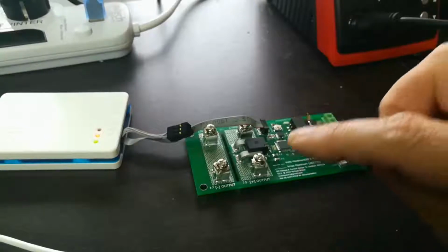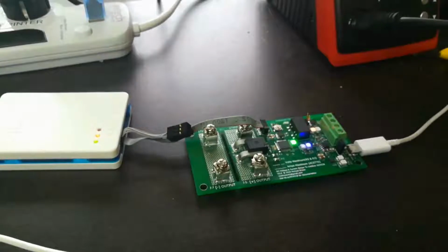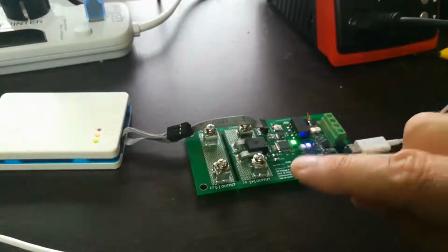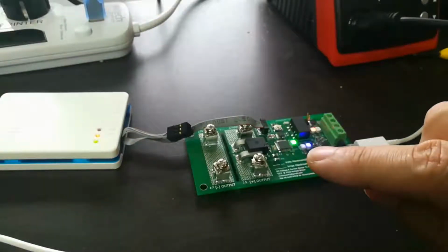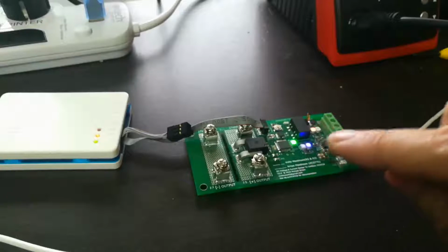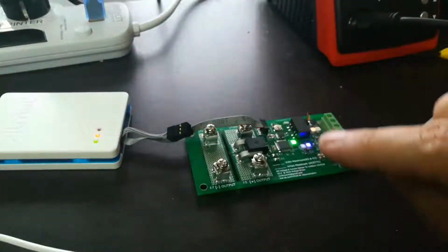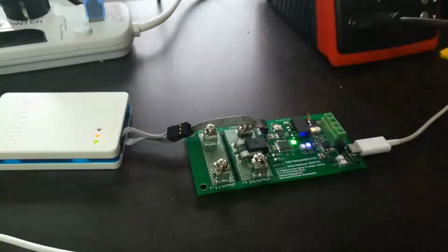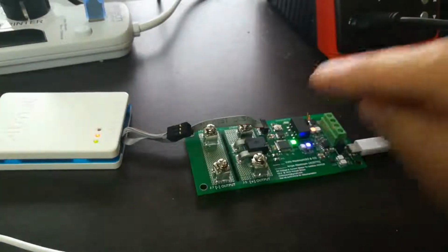Now, some of the family of chips, the ones with the package with more pins, they actually have an erase pin, which you can manually trigger an erase of all of the code in the chip and basically start as if it was from the factory. The debugger doesn't have the ability to do that for you, and unfortunately my chip does not have the erase pin. So I thought, oh, all right, I need to unsolder this chip and put a new one in.